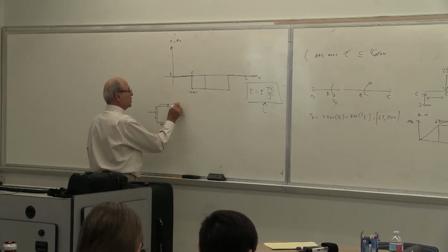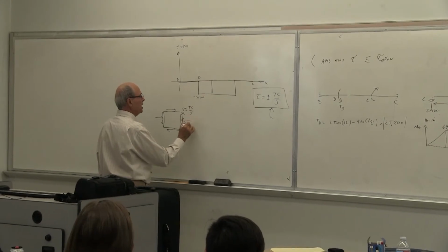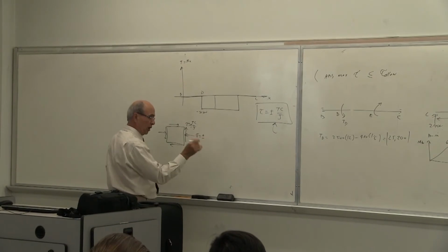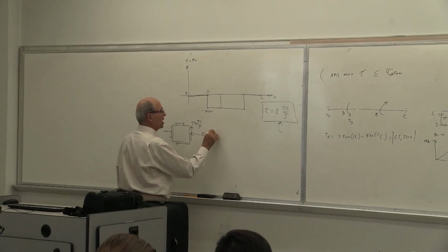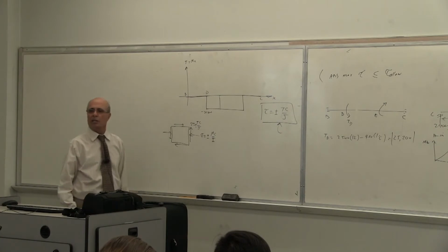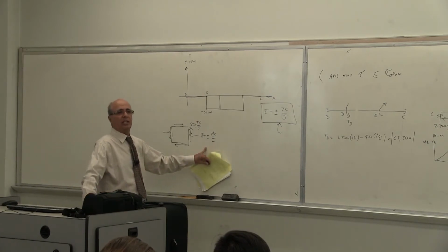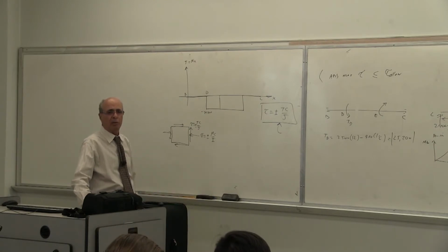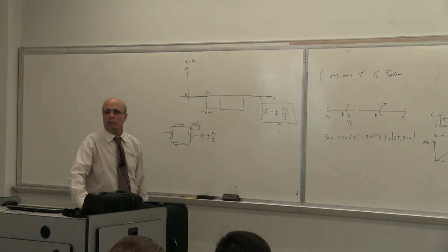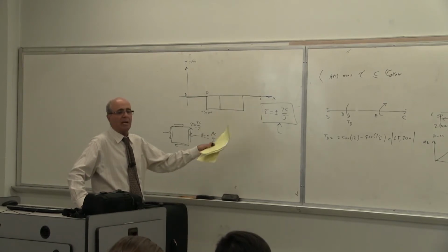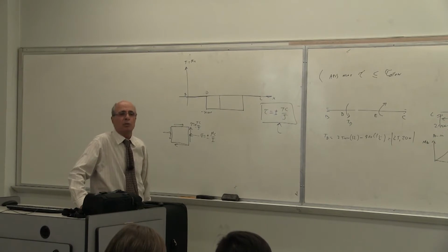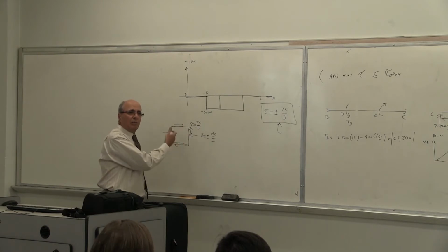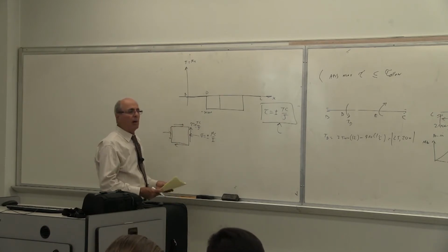This is tau equal to TC over J. This is sigma equal to plus or minus, it doesn't matter. You can draw it either way. I'll show you the result in a minute. This becomes plus or minus MC over I, either tension or compression, on the top of the shaft or bottom of the shaft. Is that correct? This depends on the direction of the torque, either plus TC over J or minus. But this is in general theory. You get this and that, either plus or minus. Yes or no? Then what do you do? What was your next step? Draw the Mohr circle for this. Regardless of the number, how does it look?